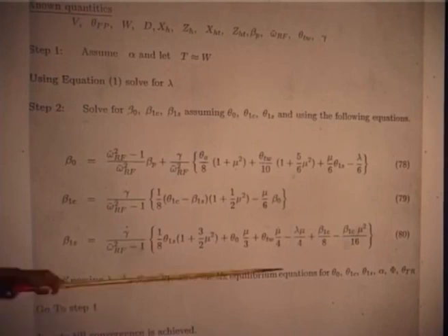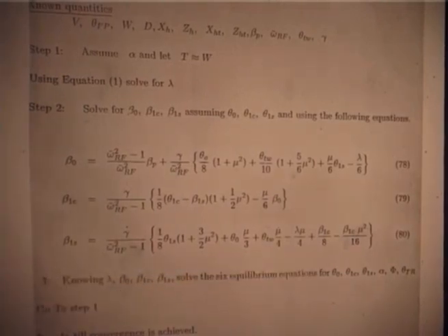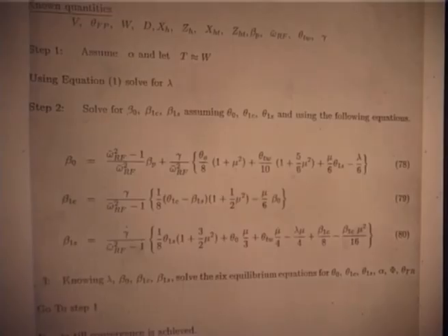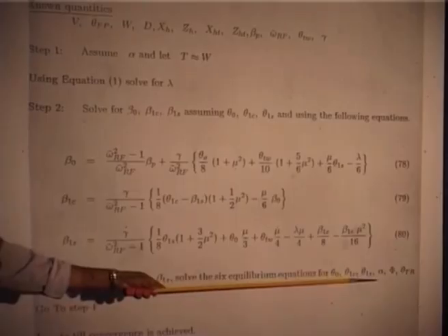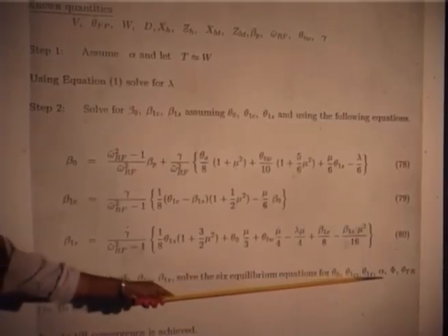Later, once the thrust gets converged, you can actually use the simplified form to get the tail rotor pitch angle. Now, when you solve these 6 equations, 6 unknowns, they are all algebraic equations. Please understand, they are all algebraic equations, but they may be non-linear. But after getting theta naught, theta 1c, theta 1s and alpha and phi, you again go back to step 1, because now you know alpha. Okay.